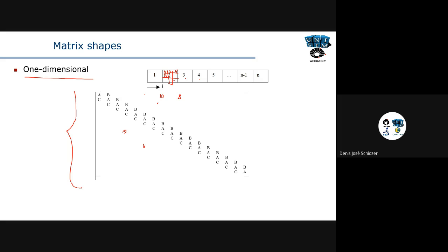So once we have a refinement here, we're going to have a matrix that's more difficult to solve. This matrix is very easy to solve for those who are familiar with this type of solution. Notice that a tridiagonal matrix like this one is easier to solve than a sparse matrix here, okay? But remember that this matrix that we are gonna solve is a function of the grid. That's why we have to select the grid very carefully, because the matrix will take more time or less time to solve according to the choice of grid.